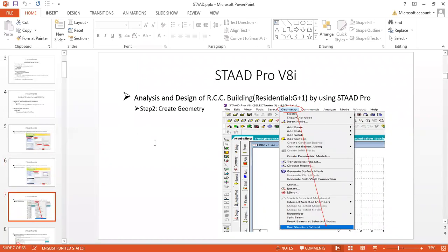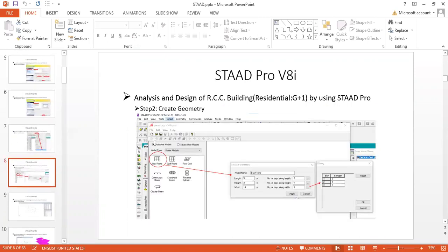We can complete the 3D modeling by going to the menu Geometry, in which we can run a Structure Wizard, where you can have some predefined structure frame systems: bay frame system, grid frame system, floor grids, some continuous beam, cylindrical frame, and many other options.